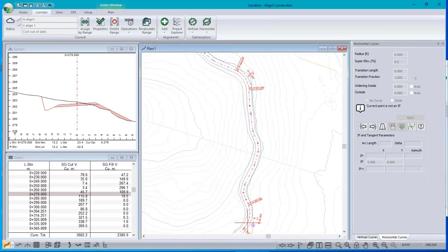There's a lot of applications for resource roads where this is the kind of road they want to build. Sometimes, like I said, in the tropics, it doesn't matter where you are. You have to use full bench because the ground has poor integrity. Here on the coast of BC, and in fact, that's where this LiDAR came from, the problem is that the fill becomes unstable.